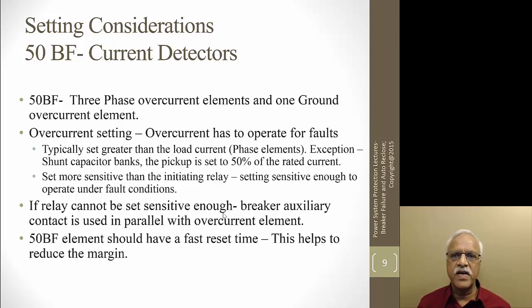You cannot set the breaker failure time to less than your relay operating time plus the breaker operating time plus the overcurrent element reset time. So sometimes if you have a good overcurrent element which can have a fast reset, it allows us to reduce the margin.